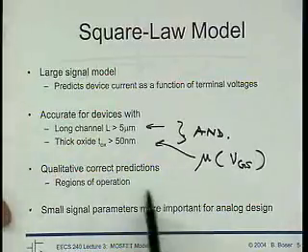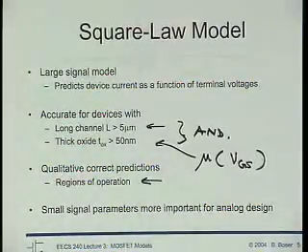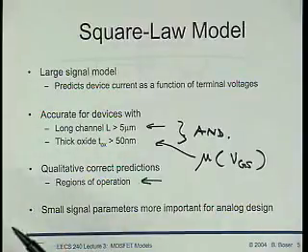Okay, I've already said that regions of operation and so on, of course, are a little bit fake too, right? I mean, the device doesn't go, suddenly you apply the threshold voltage to it, and it goes from one region of operation to something totally different. That's also not physical. But the notion of these different kinds of regions, like a linear region or saturation, where the transistor can operate like a resistor, or it can operate more like a current source, that really is a useful qualitative description, and we'll keep on using that.